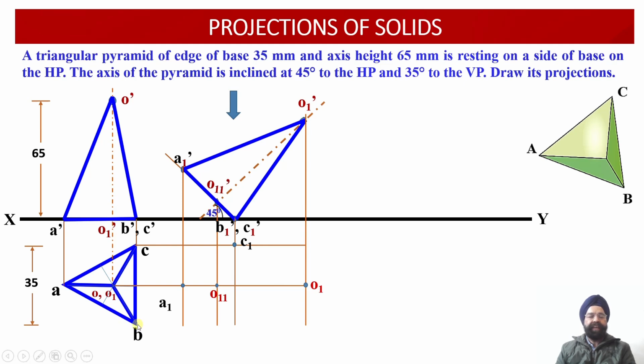And finally, here we have the point B corresponding to the plan projection view. Now from this point, we are going to draw another horizontal projector line and extend it up to the limit where it is going to intersect with the vertical projector line drawn through the point B1 dash of the elevation. So this way, all the 5 points of the plan projection view have been obtained.